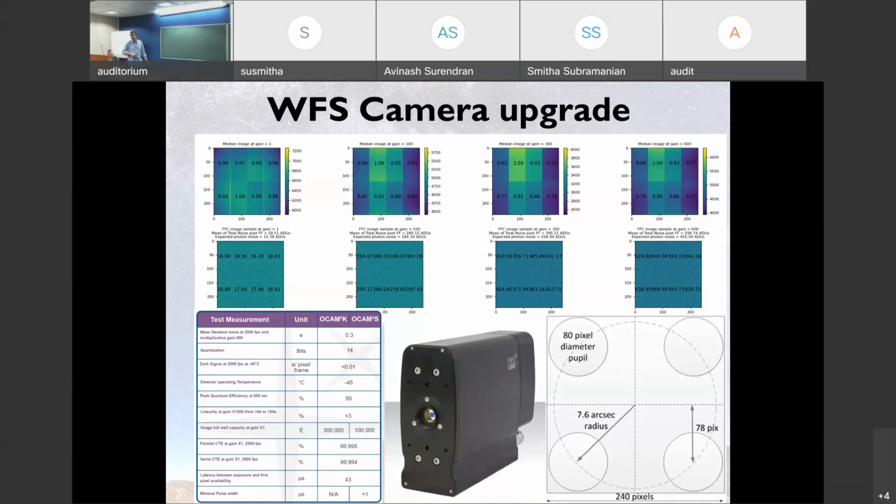That is one problem with these cameras, one of the problems we are facing with implementation. If you are suddenly going by a cloud or something like that, the over illumination protection of this camera kicks in. Ideally we want to use it at the maximum gain of 600, where we get maximum signal to noise ratio with respect to readout noise.